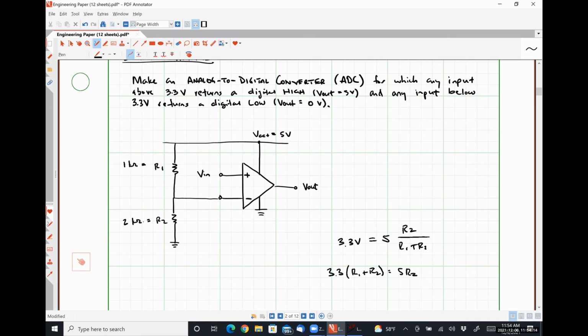So we can establish our bias voltages, or our reference voltages, by using a simple resistor biasing network so that we don't need an actual extra power supply to set this up. But it only works if we choose resistor values that are not of the same scale as the internal resistances of our op amp. All right, that's enough out of me for today, unless you guys have another question.